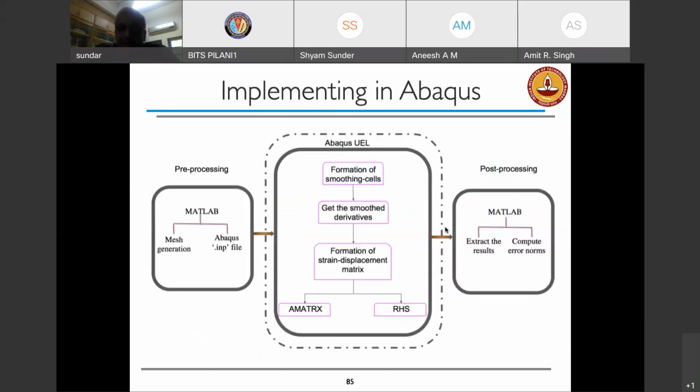So what we have done successfully is that we were able to implement almost all of them except for isogeometric analysis. We have implemented scaled boundary, smoothed finite element method, polygonal finite element method, even XFEM within Abaqus. Of course, XFEM is now in Abaqus as a part of the module, but the rest are not there yet. But it is possible to cheat Abaqus in solving problems using different methods.